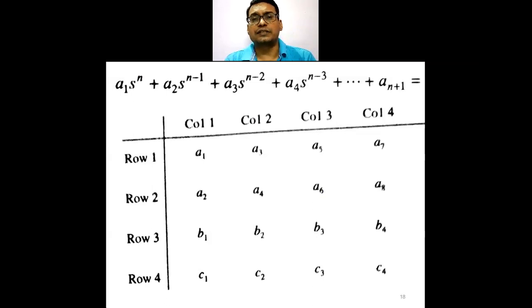The open loop transfer function is the feedback disconnected from the comparator, that means the product of all transfer functions in a control loop. So 1 plus the product of all transfer functions in a control loop is your characteristic equation.